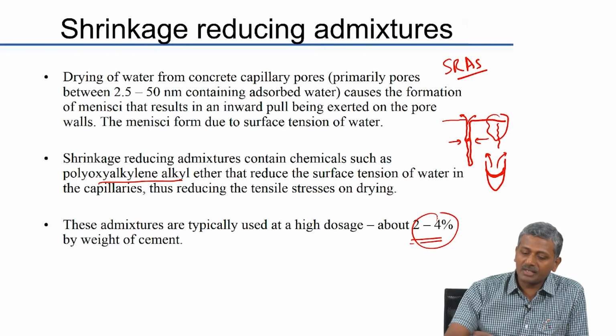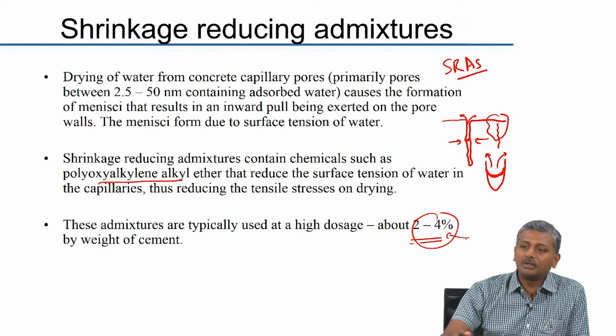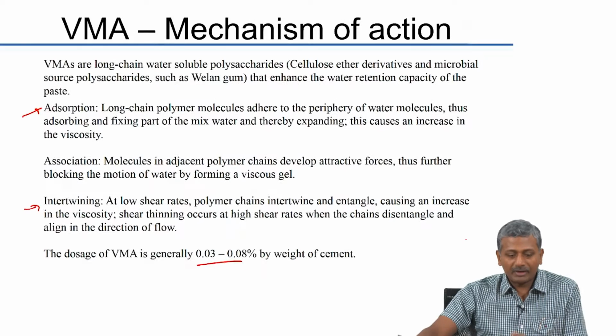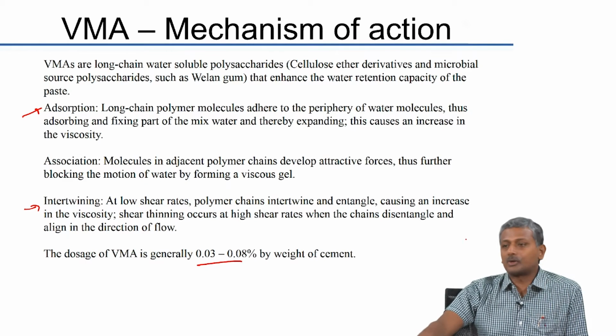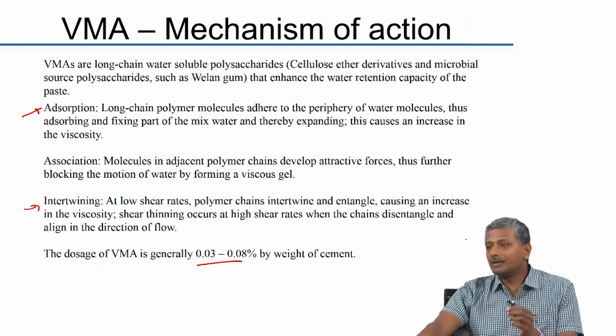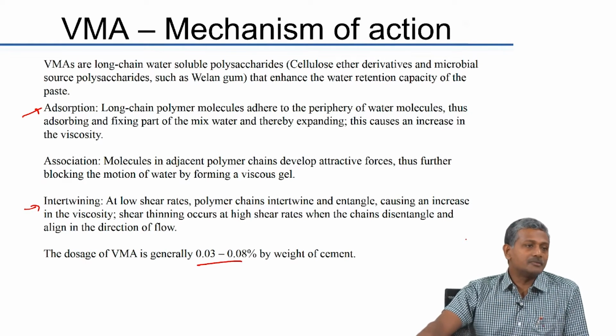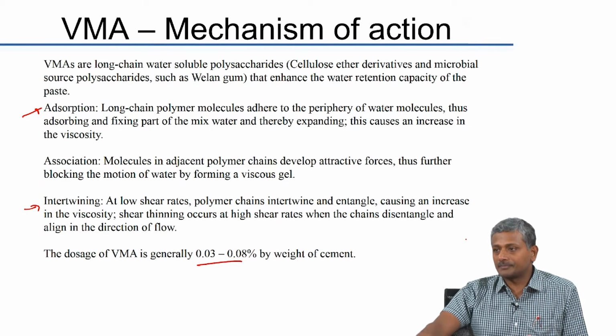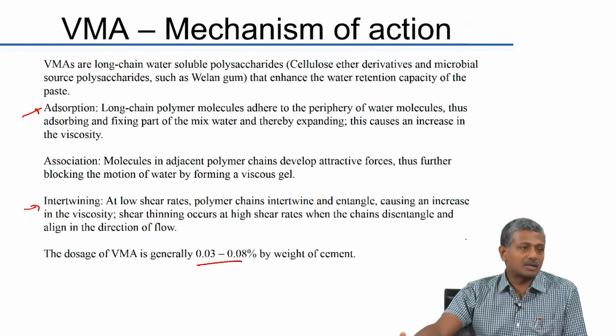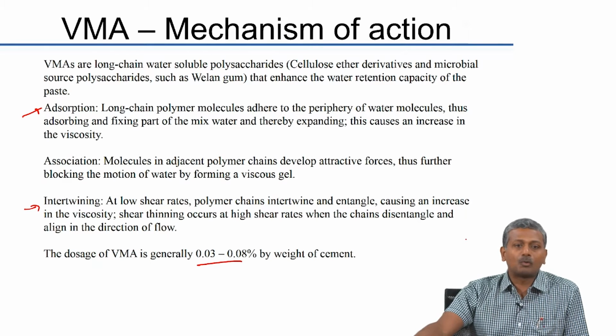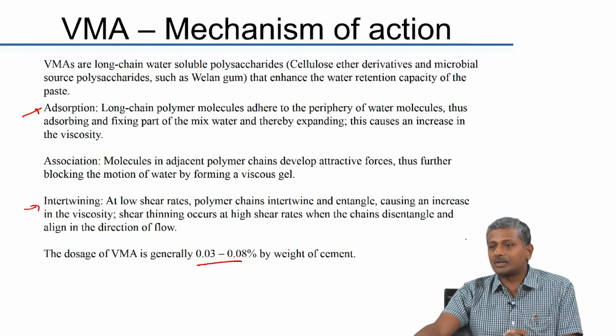Okay, when I am talking about these dosages, they are in terms of the liquid. However, when I talked about the VMA dosage, it is in terms of the solid, because most VMA is available in terms of solid formulations of the gums, which could be stabilized by making them into liquid solutions also, because the construction chemicals industry basically wants to sell all their products as liquid, so that on site there are no difficulties in dispersing the chemical.